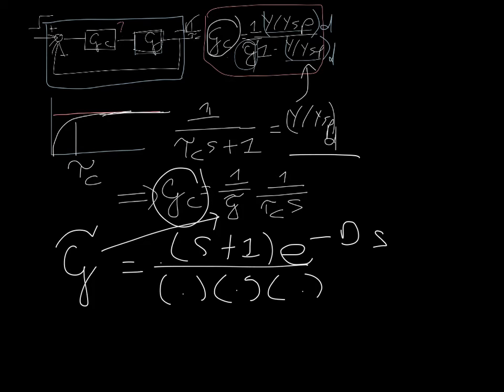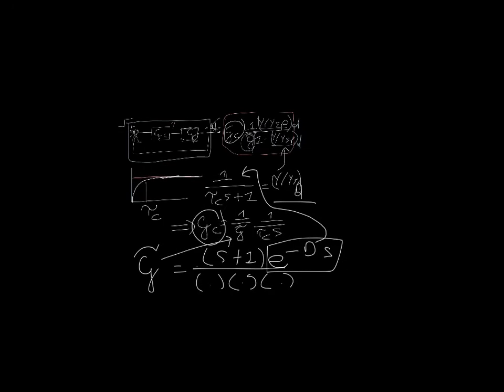So in practice, if we see one of these, we have to take that into account in the original desired output. We have to live with that delay. We cannot remove the delay by incorporating control. So we'll have to accommodate the delay in our desired output, and that makes our life a little bit more difficult.